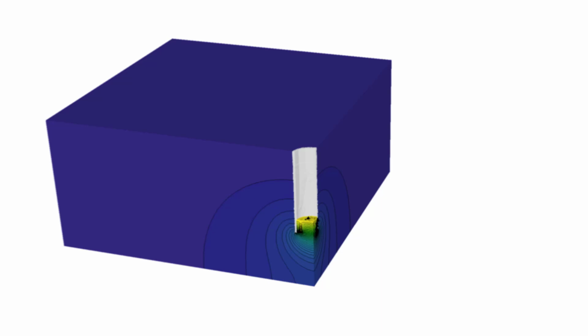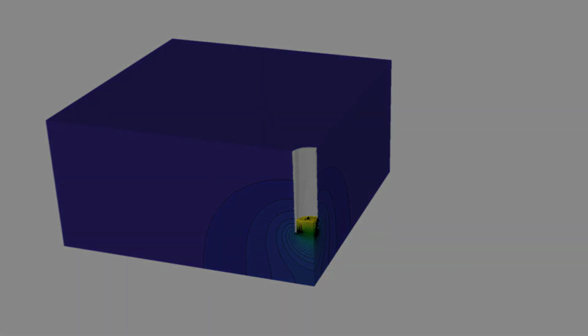As expected, the head loss is largest as water moves upwards towards the base of the excavation. This warrants further investigation as it may lead to boiling at the base of the excavation and heaving of the entire mass between the base of the excavation and the base of the shaft. So what exactly is boiling and heaving? Well, to answer this question, we need to toggle back to the slides and return to the basics.